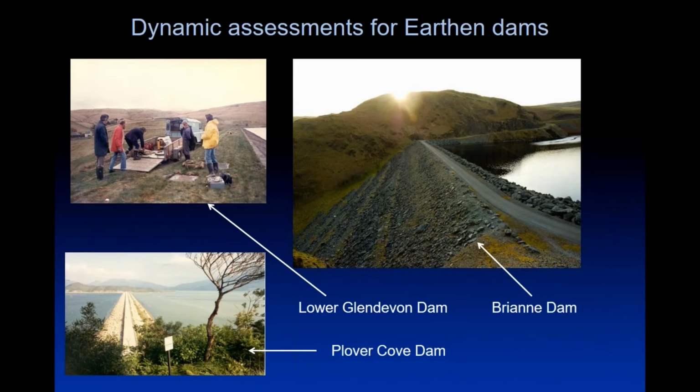Briani Dam, there was no real problem with it. We shook it, we got the characteristics, and it emphasized that the sorts of things that we've got from earthen dams are general. You can take it from one dam to another. So now, we don't have to use a vibrator system to shake a dam. We can use ambient excitation. And in fact, we use that for all of the structures that we've got.